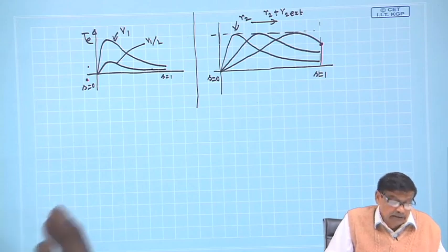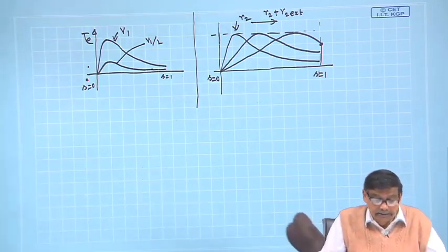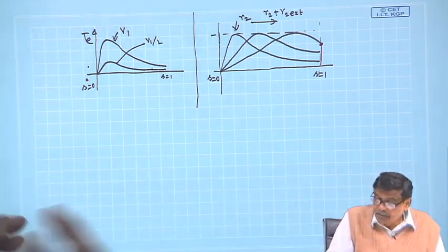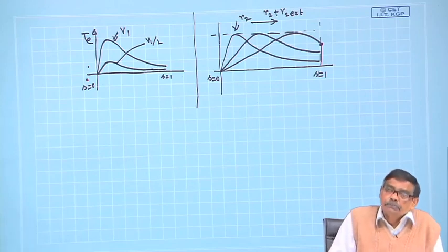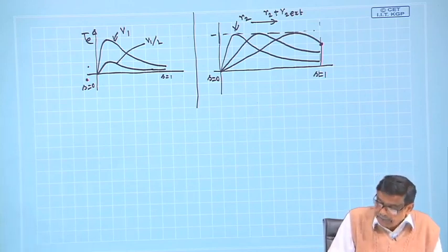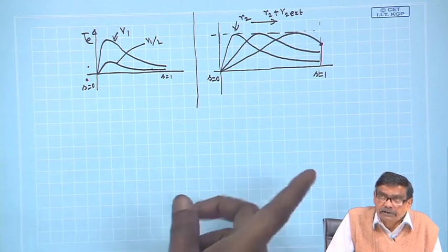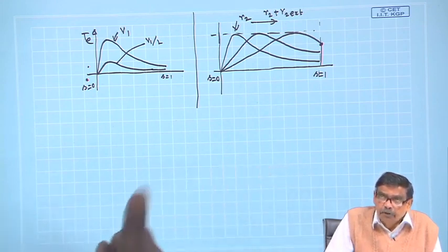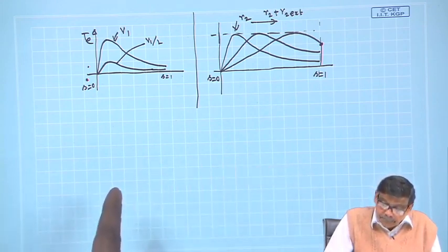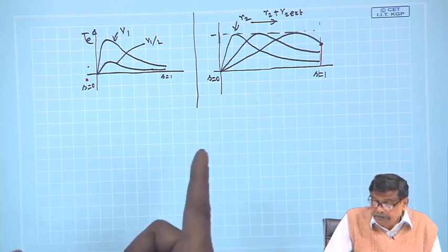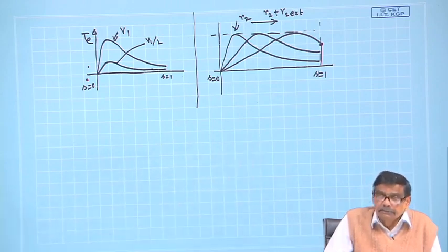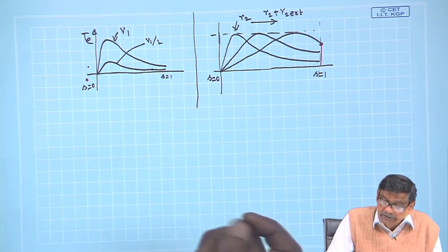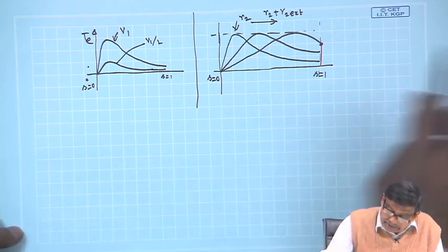So, remember one thing is important, that rotor resistance should not be kept permanently connected. That is, you connect R2 external, exploit that you can get higher starting torque. Depending on that, you select R2 external, connect it, no doubt.